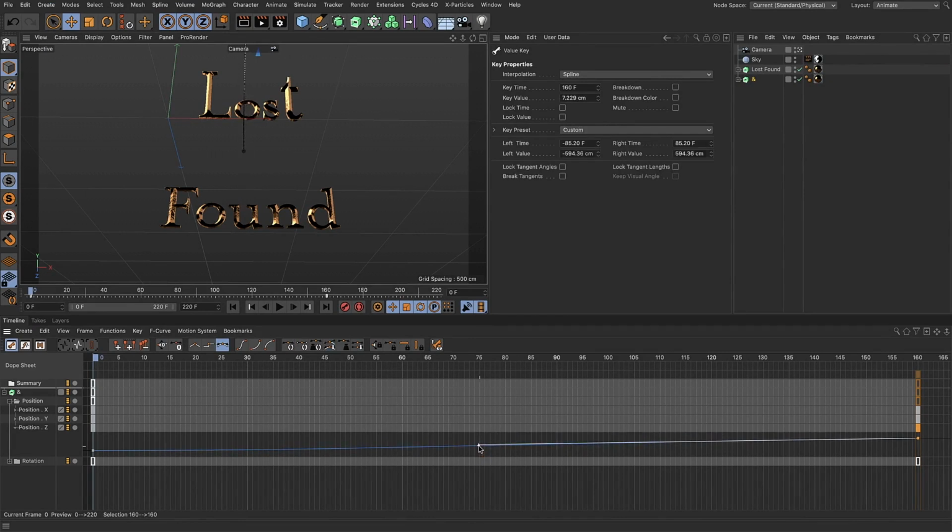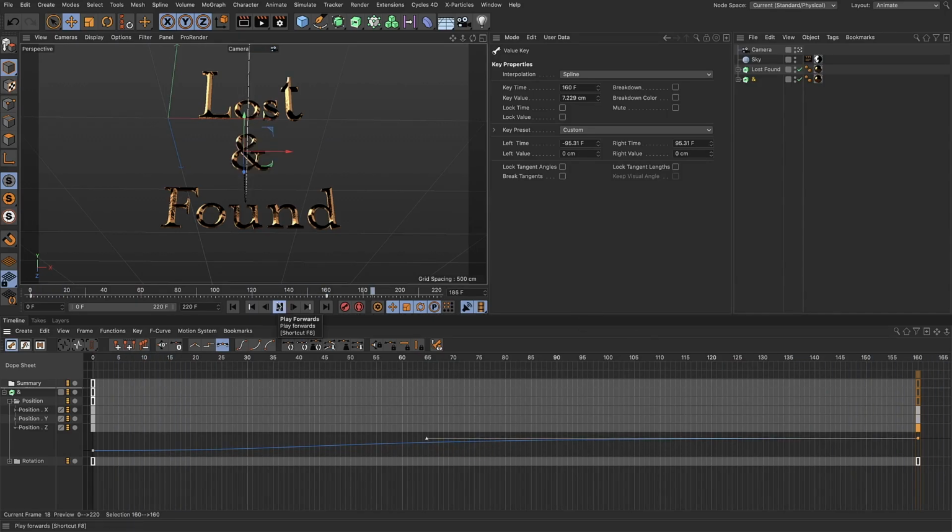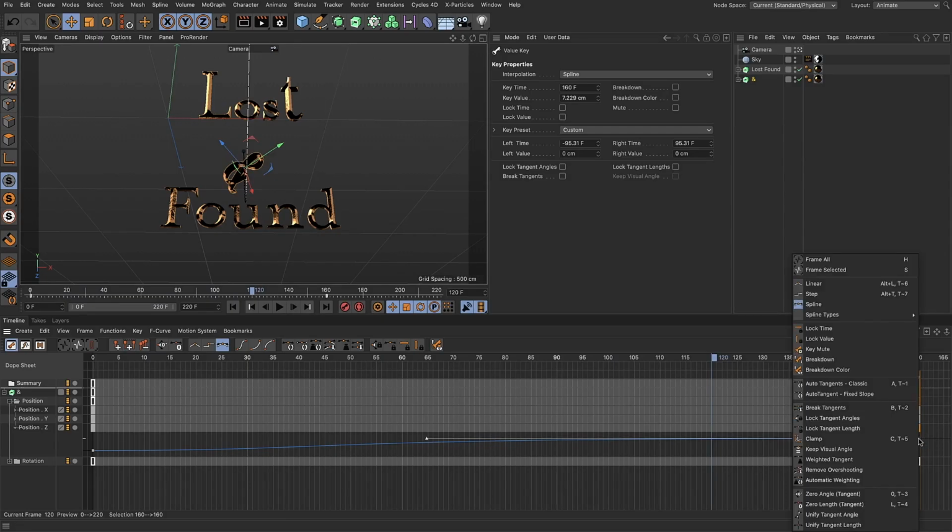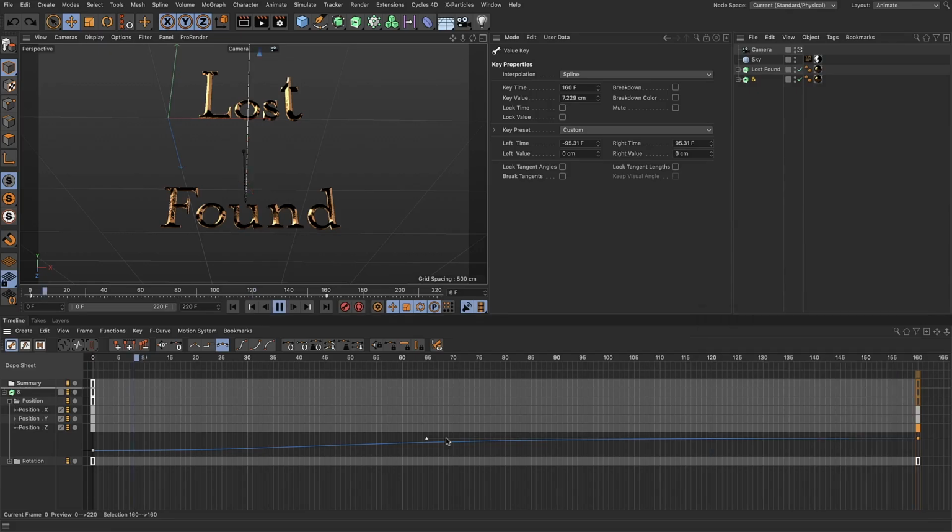path of motion. I'm going to just press the space bar in order to play back, noting that that is a little bit too high off screen. And I'll come down here and adjust this accordingly to change that motion path of the AND symbol. I'm going to pause to stop, and I'll now just right click this keyframe to show that you can choose from a series of spline types. So we'll leave that there for the AND animation's path for the time being.